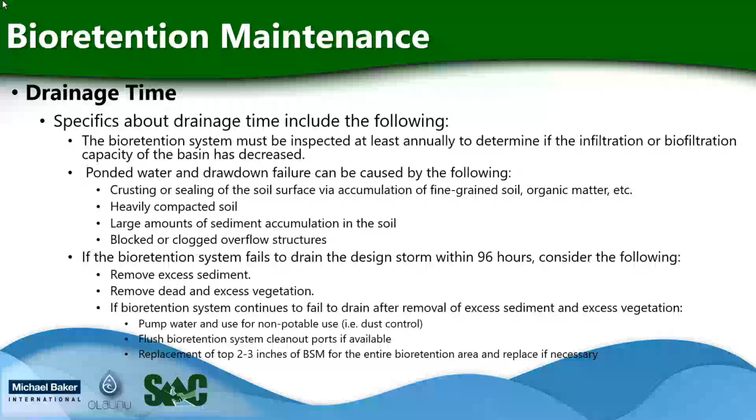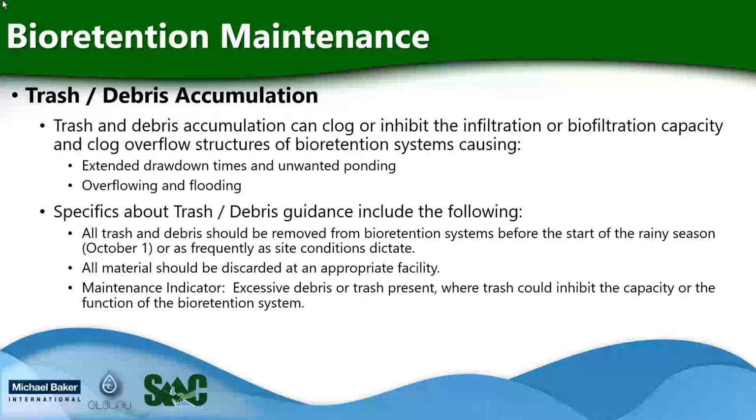Trash and debris accumulation is also an issue as far as maintenance. That can clog or inhibit the infiltration or biofiltration capacity and clog overflow structures, which can cause extended drawdown times and unwanted ponding, overflowing, and flooding. Specifics about trash and debris guidance include the following.